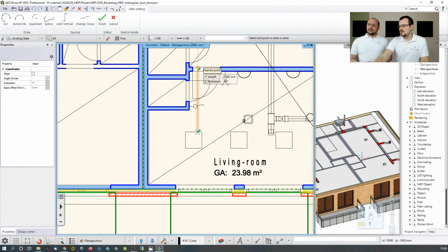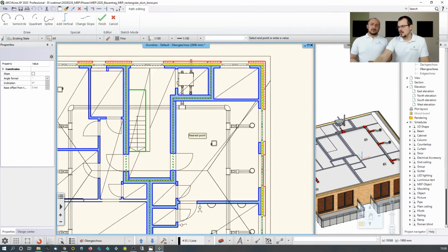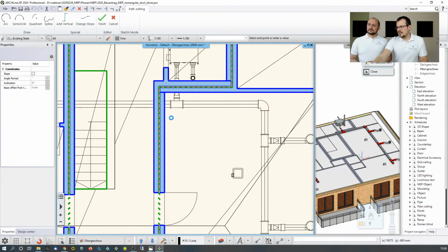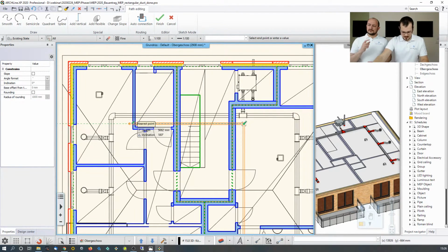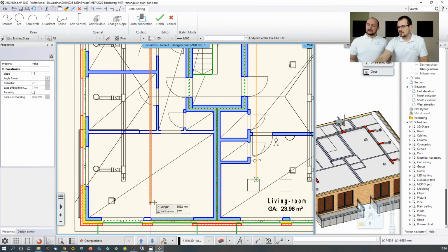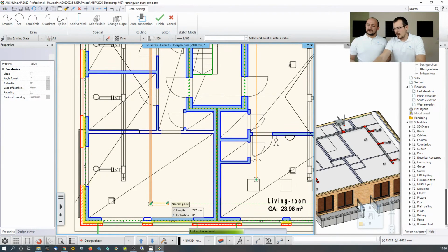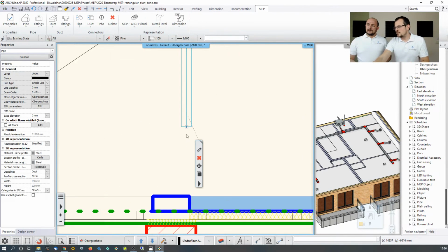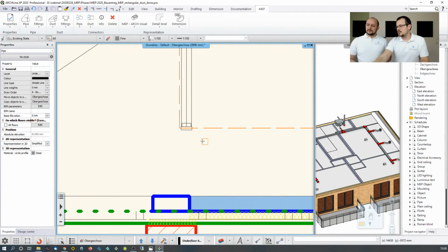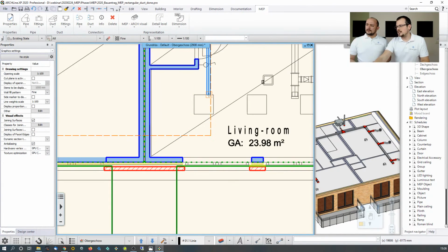So this is going to look like drawing this. It looks the same. It's not different at all. One thing I have to figure out once I have drawn it is its base elevation, because again this is going to be on a different height than my other ductwork. So I'm just going to do it like this. Again, before I forget, I'm going to cap it off. This time I'm going to do it in the 2D. So cap one end, and I'm going to cap the other one.